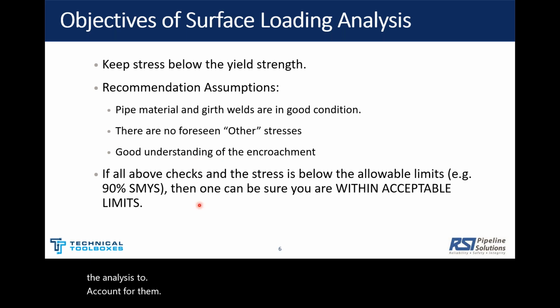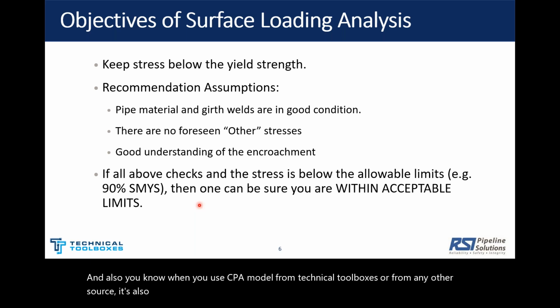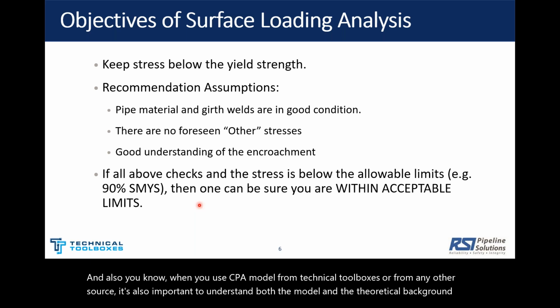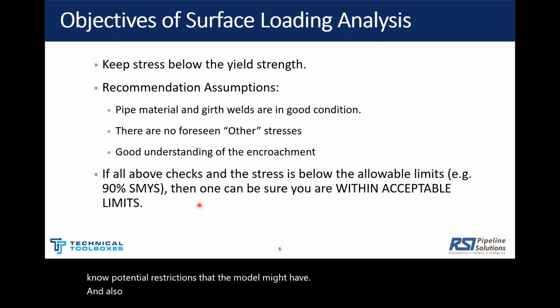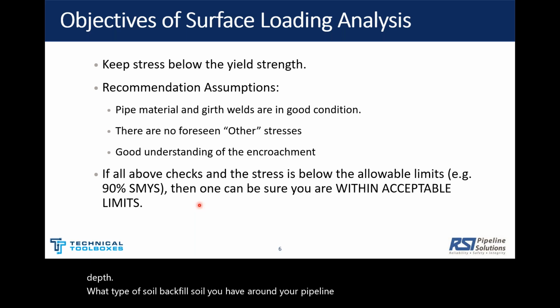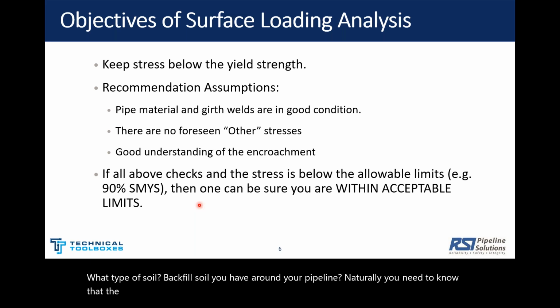And also, when you use a CEPA model from Technical Toolboxes or from any other source, it's also important to understand both the model and the theoretical background, potential restrictions that the model might have, and also to understand details of your encroachment problem, right? Such as your cover depth, what type of soil, backfill soil you have around your pipeline. Naturally, you need to know the characteristics of your pipeline, such as diameter, wall thickness, etc.